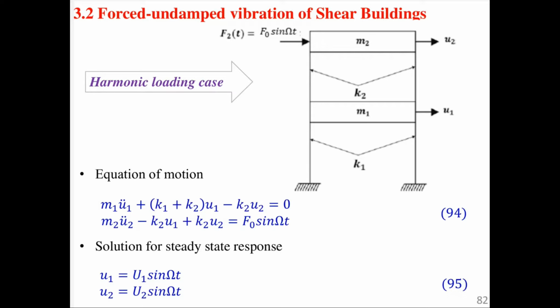Basically, for free vibration, we usually start with that for ease of understanding, because components like damping and externally applied force are eliminated, and it makes it easier for us to analyze our structure. But what you realize is that most of the significant vibration you will encounter in real life cannot be free, or generally will not be free, because we'll be considering earthquake, wind loading, or a lateral force like an impact load.